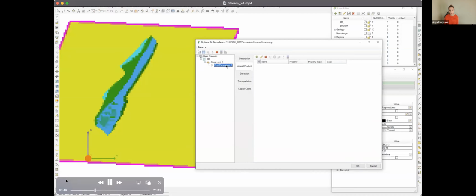For all the areas that are not covered by wireframes, the default angle would be 42 degrees, but it will not be used since they created geotechnical wireframes that cover the open pit. So the next step is adding the final product's name and its cost.